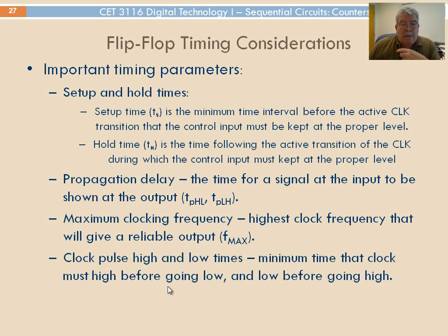Another important parameter that is given as well is the clock pulse high and low times. Not necessarily, in the very strict sense of the design, do both need to be the same size. In other words, I mentioned that the proportion or ratio at which the clock remains high and remains low is what is called the duty cycle.